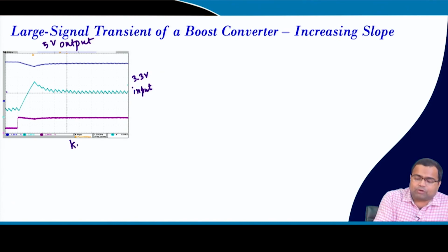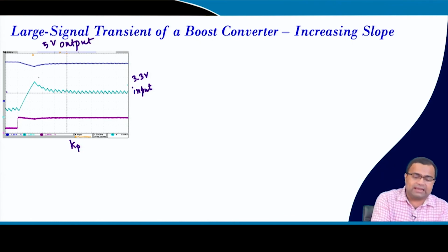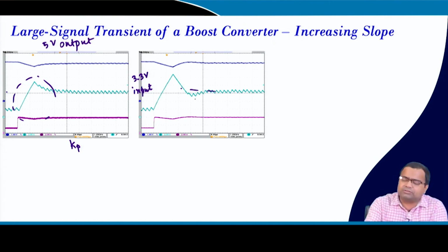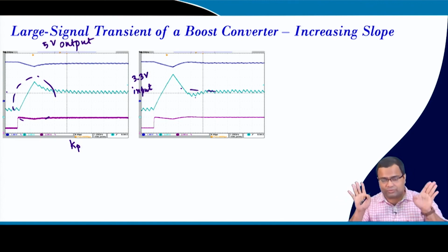Here we take a smaller Kp because I am just playing, but we will formulate for the buck converter more elaborately, and we will give an expression for boost in the subsequent lecture. But what we did by this formulation: if we take a smaller value of Kp, you can see it is not the optimal recovery because there are a few more switching numbers. But if we increase Kp to a proper value, it is more or less optimal, because you see there is a slight overshoot and undershoot in the current, but this is close.